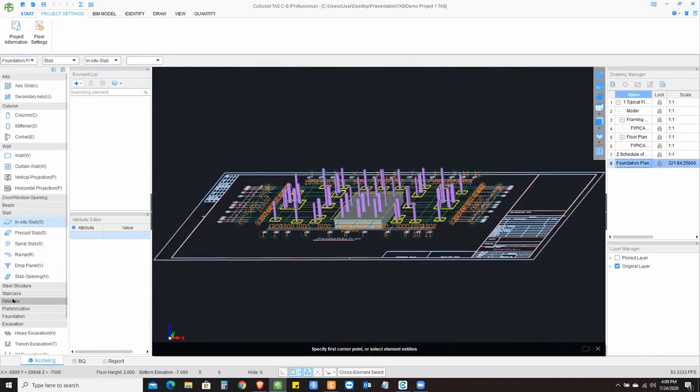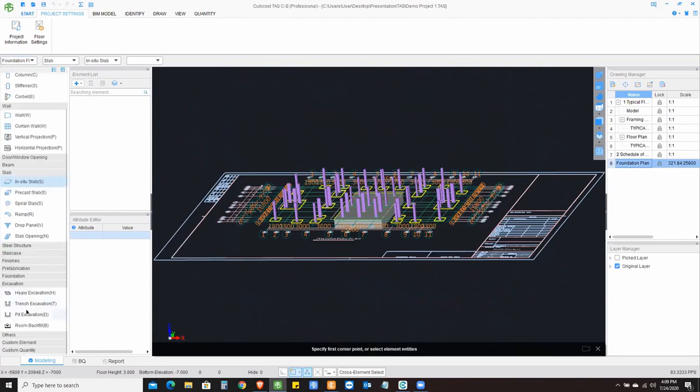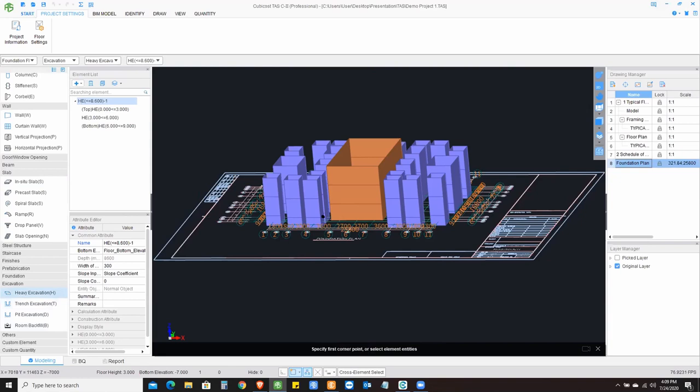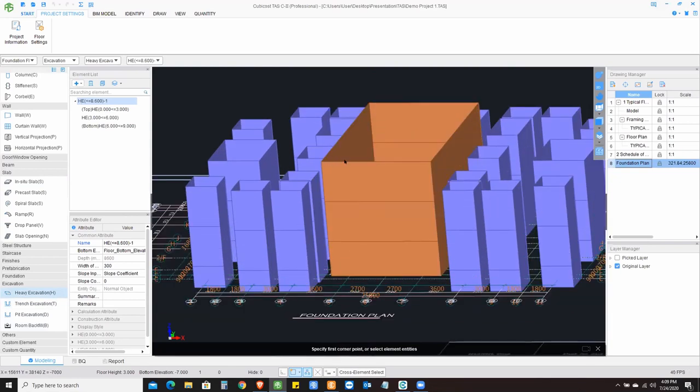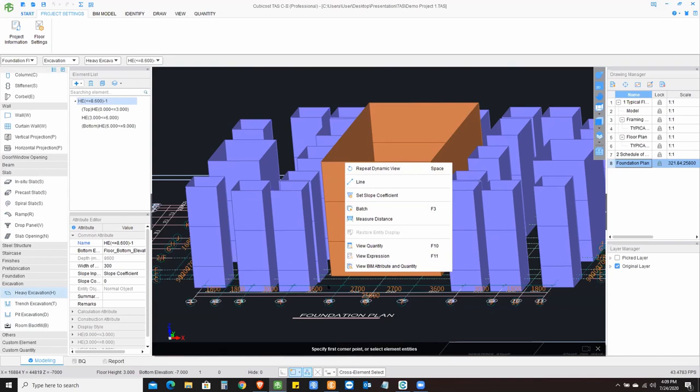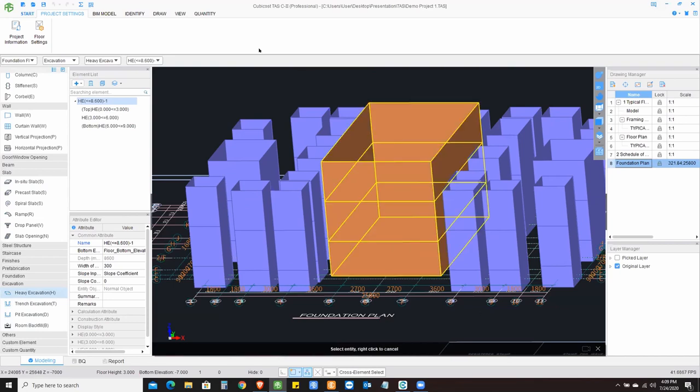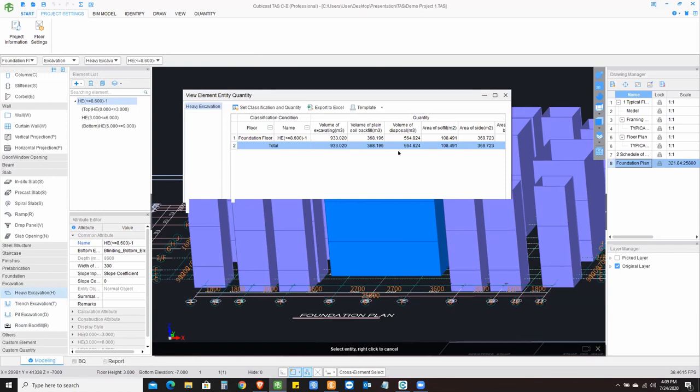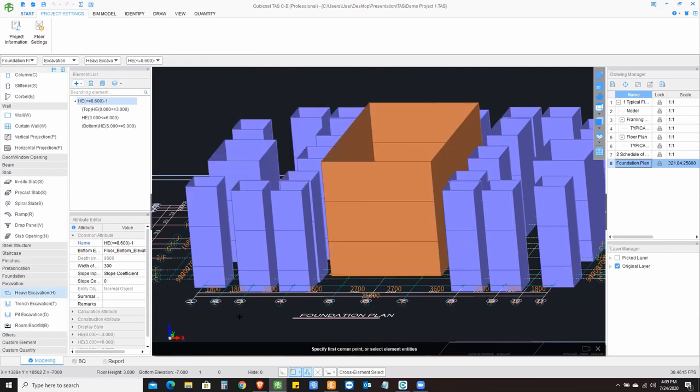Now, if I go to my excavation, which I've got here, the excavation, I believe, yeah. As soon as I calculate the excavation, you'll get the disposal amount, you'll get all the amounts based on the excavation quantities. But then if you want to categorize it based on your different materials, then you need to do it manually. What I mean by that is you need to apply the elevation of each of these excavations based on your control levels or based on your material type.